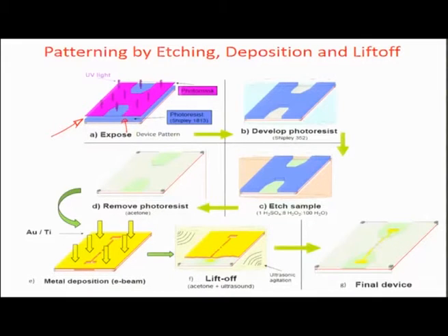through lithography. So, this is a resist, it is a Shipley positive tone resist which gets debonded on exposure to light. There is a mask which has been kept. So, the resist is patterned here, opening vias, and the gray layer which is underneath the blue photoresist layer gets etched off because of the opening of the windows in these two regions, and the resist acts as a sacrificial material, thus exposing the green area now, which is just underneath the gray area.